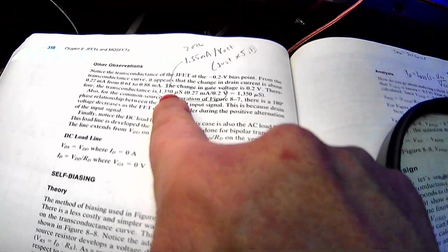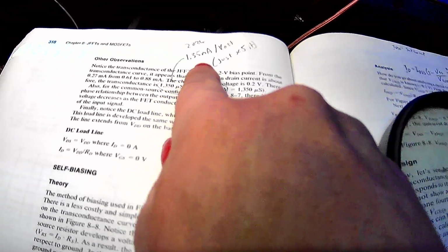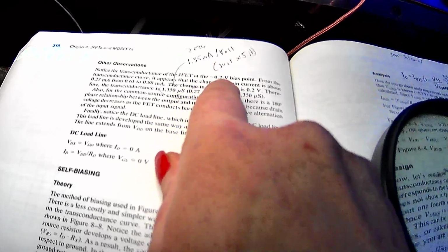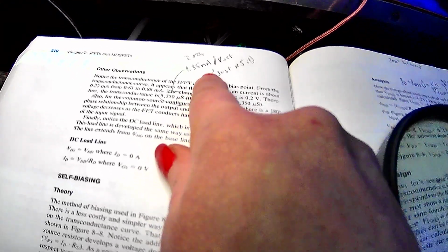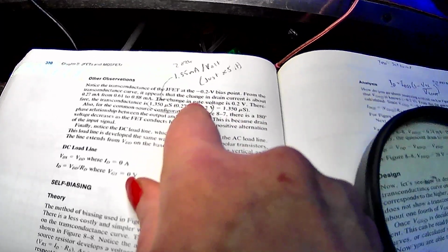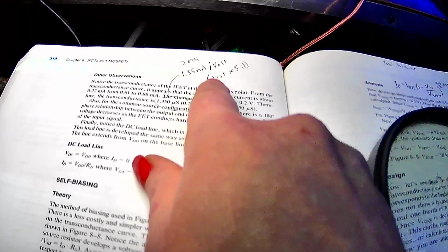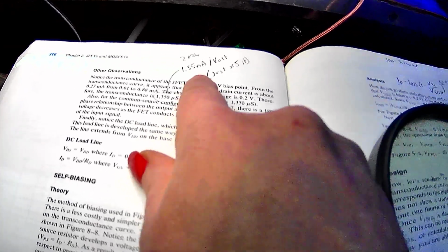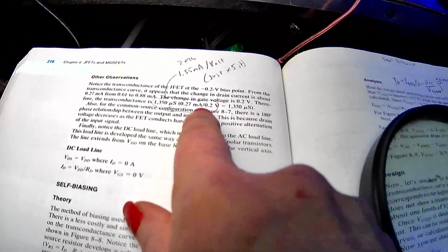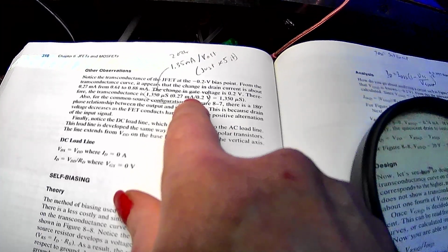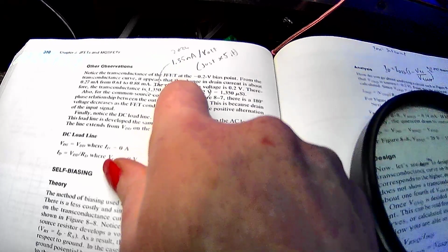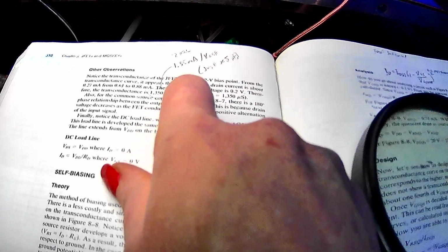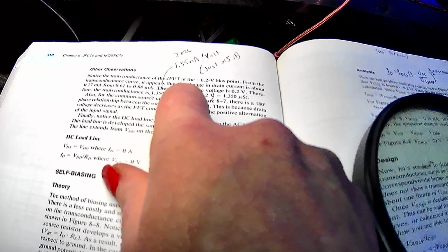But at any rate, like I said, if you've got a millisiemens, it's pretty much like what they're talking about here: 1350 microsiemens. Well, that actually works out to 1.35 milliamps per volt. So you can get that idea that that's a good way of looking at millisiemens. The transconductance figure is a certain amount of current per volt, because it's a voltage to current amplifier. That's transconductance. But this helps materialize this microsiemen, millisiemen business, in that basically for every volt you'd have 1.35 milliamps change for every 1 volt of input.